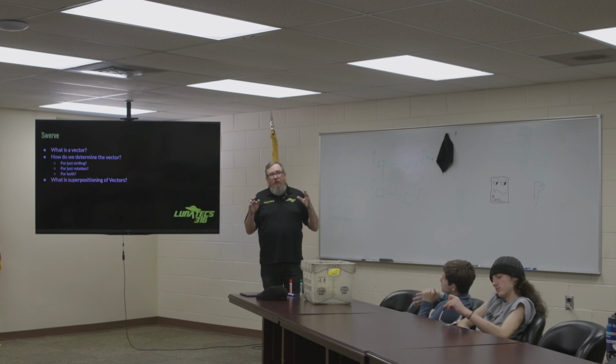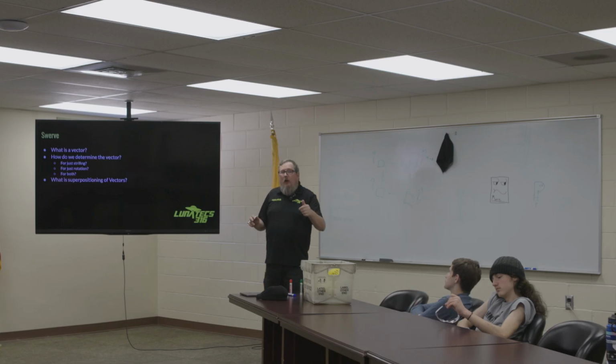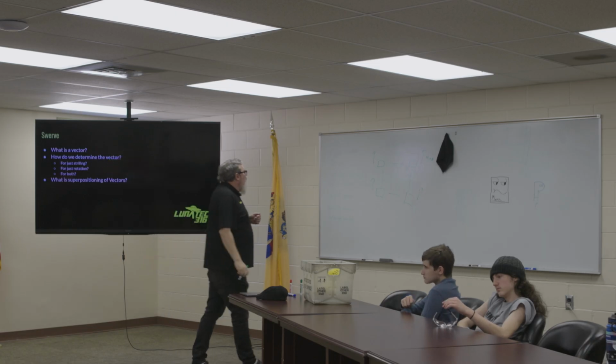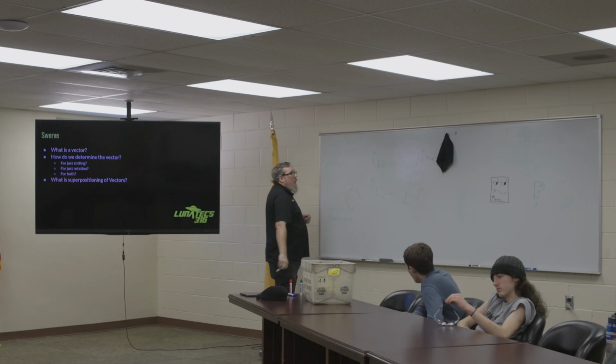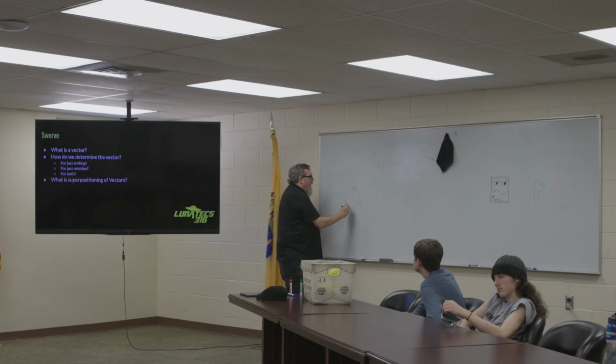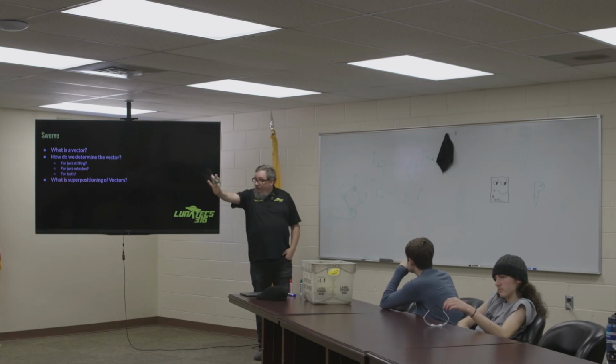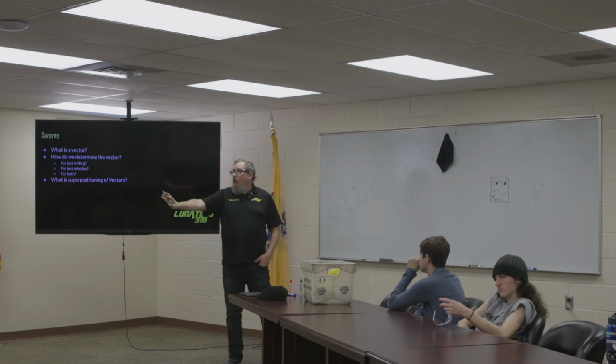For our purposes, we do field oriented. So if I press the robot forward, all the wheels will face away from the driver and it will move away from the driver. Does that make sense? So if the robot is like this, and this is downfield, the orientation of my wheels will be like this, right? Because it's going away from the driver, because that's which way forward is.